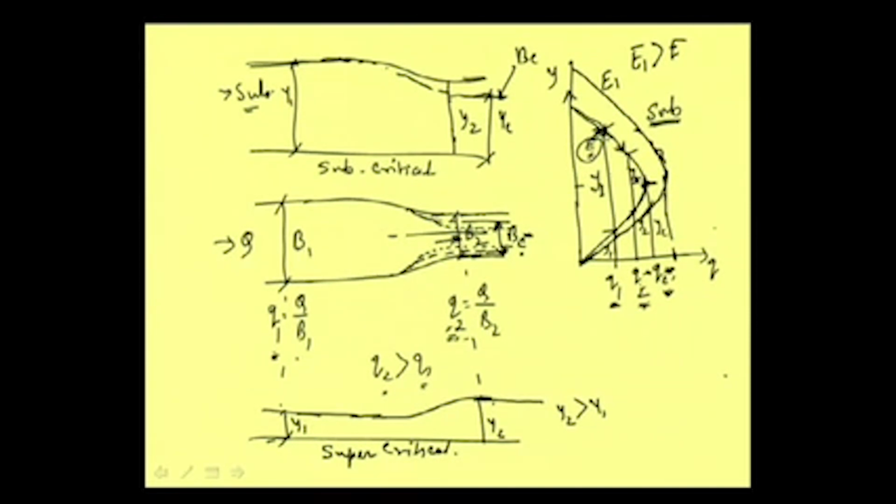So, if our B has been narrowed down further to have the discharge of this much Q, say new Q, then our upstream will be rising. So, this will remain there and the upstream will be rising in this way, and this rise will make the energy level increase here.